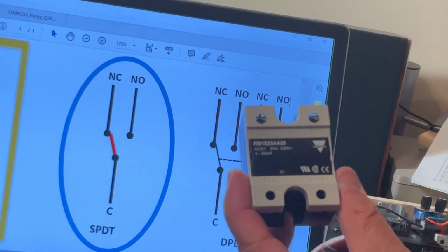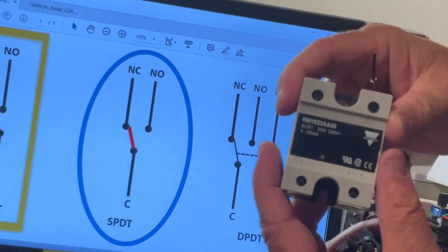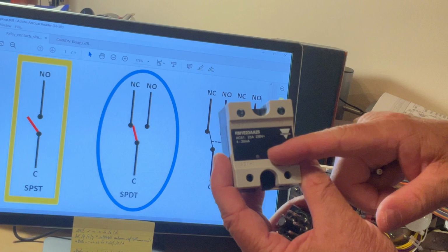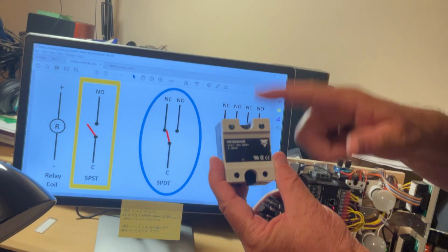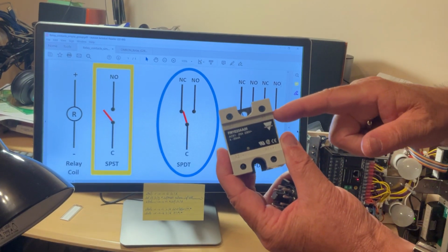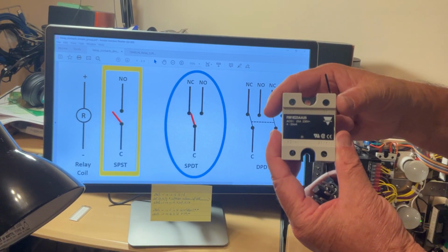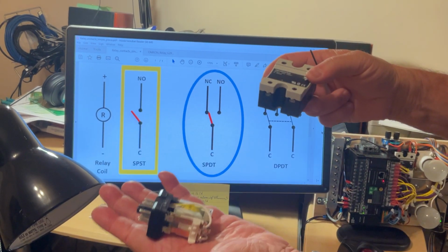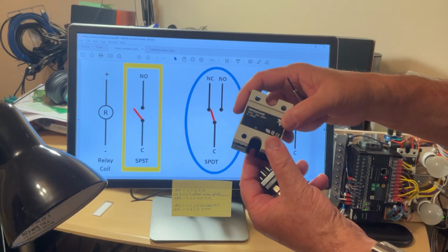And I can mention 3 kinds of semiconductors if you want. An optocoupler to make the insulation between input and output, a phototransistor, and then the assembly made of TRIACs, which is what's going to the output. So again, first classification, electromagnetic relays, solid-state relays.